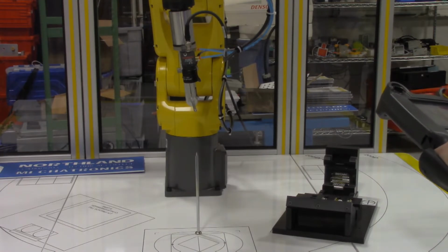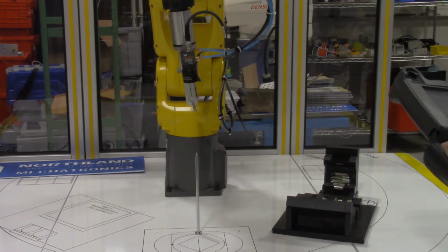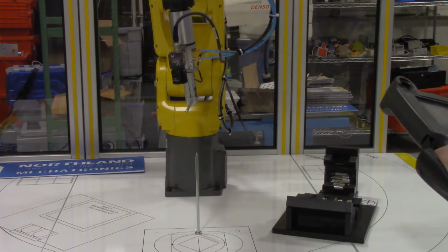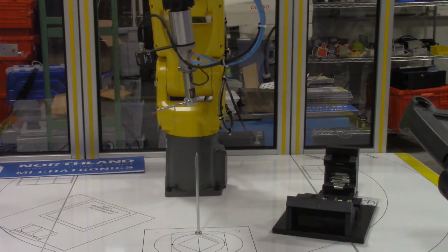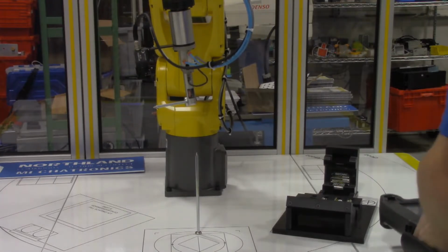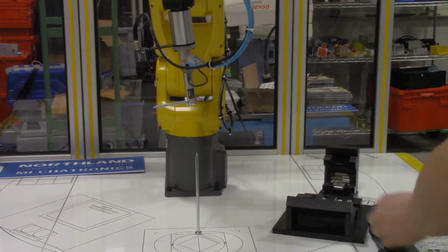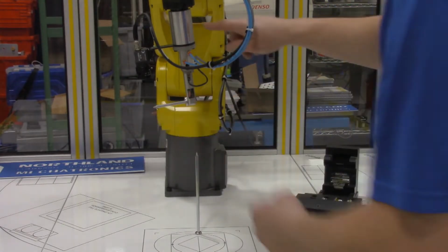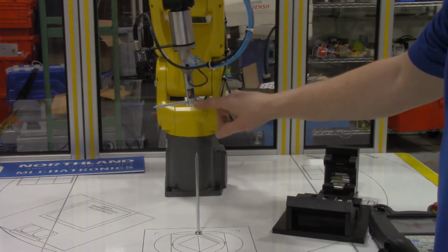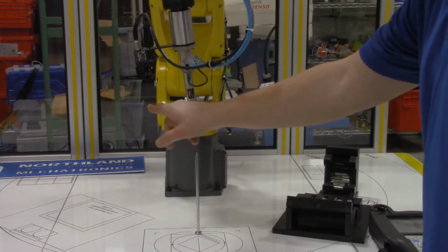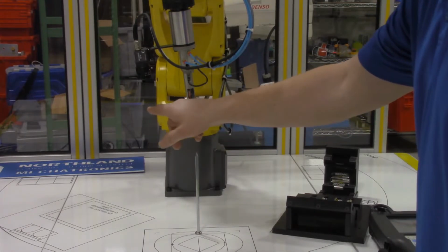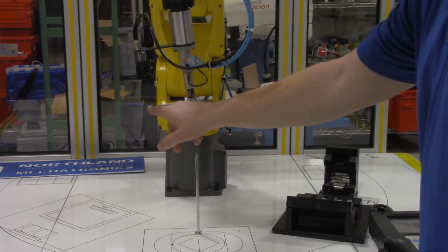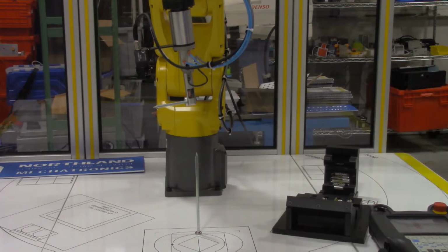Let me just put it in joint mode and rotate axis number 6 so you guys can see where that tooling center point is. Okay, so there it sits at a funky angle. So not only are we offset in the Z direction, we are offset in an X or Y direction as well. And I'm not sure exactly how it's sitting on here, but it may only be in one axis, but it's definitely offset. So we want that to be our new tooling center point. And let's go ahead and use the 3-point method to configure this.